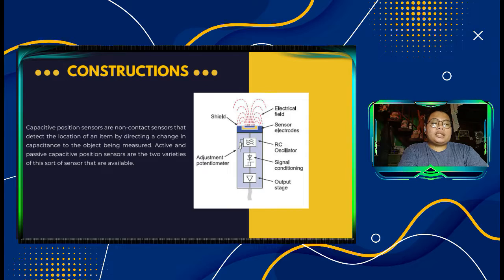a capacitive position sensor has two major parts. The first one is the active sensors. For active sensors, cable length restrictions are not applicable to the active system. Active sensors operate at higher frequencies and output bandwidths. They are also appropriate for applications like spindle run-out analysis that may involve stray electrical noise on the target.